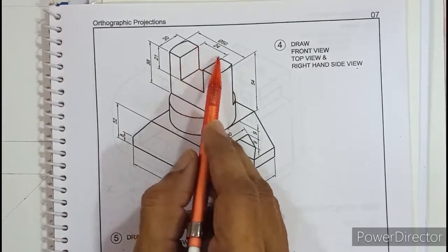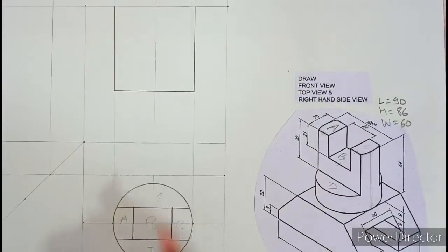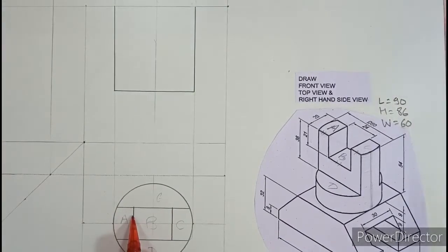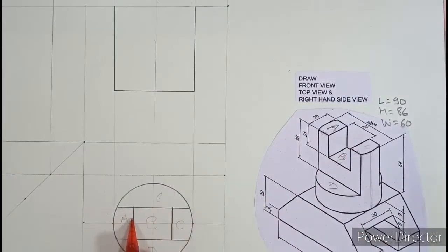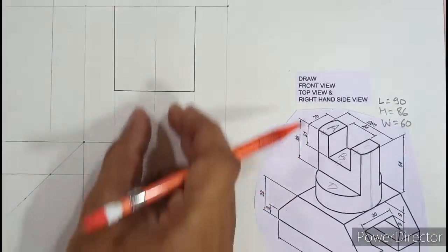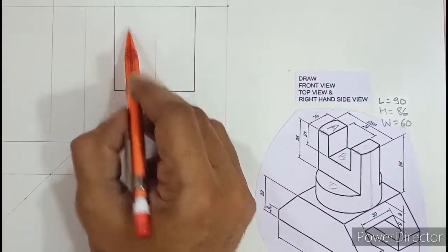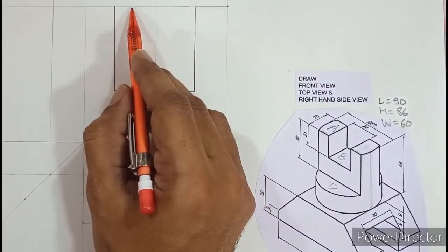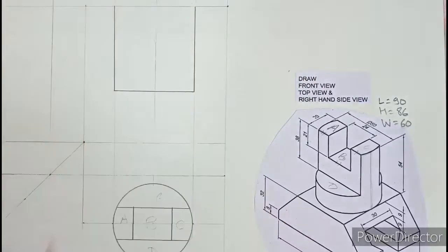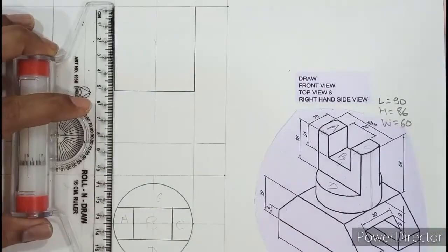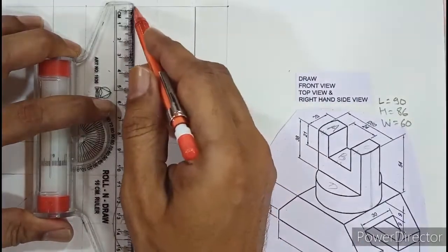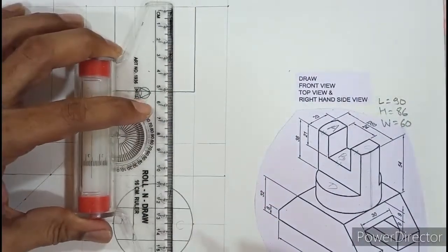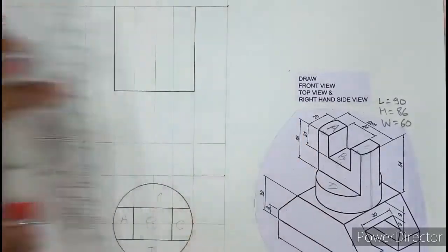But have we drawn this 24 in the top view? We need to search. So see this dimension B, this is 24 millimeter. Okay, so the same slot of 24 we have already drawn here. So if I extend this to 24 up, will I get a cutout over here? Only thing is that you need to produce it till a depth of 21. So let me align the roller scale and project this A. Projection is compulsory to learn orthographic. So you should know what to project and when to project.